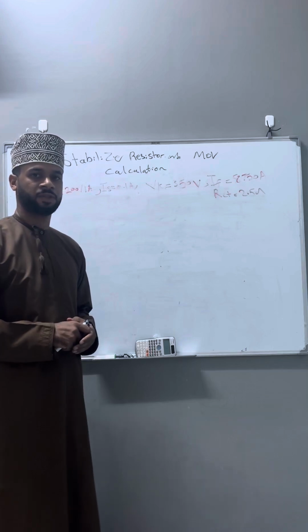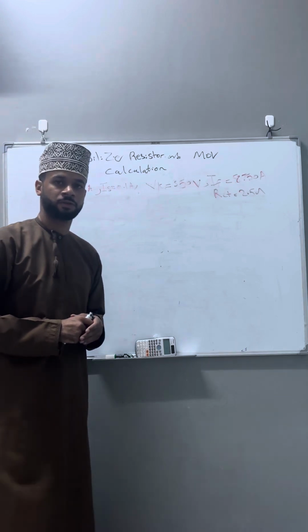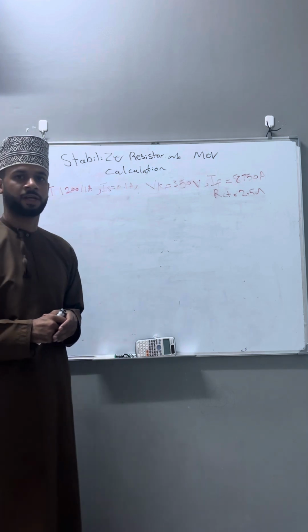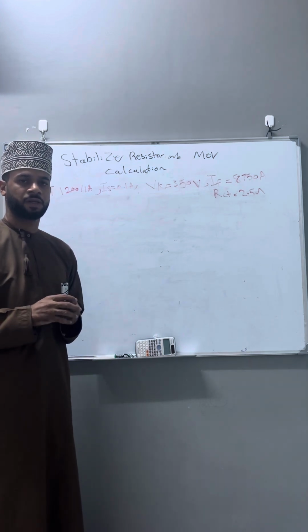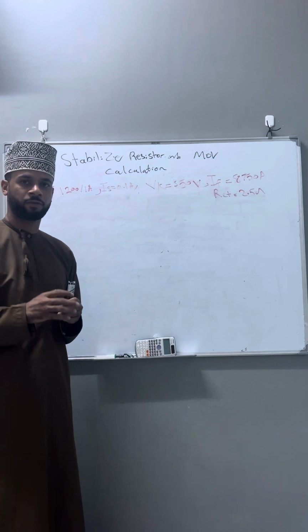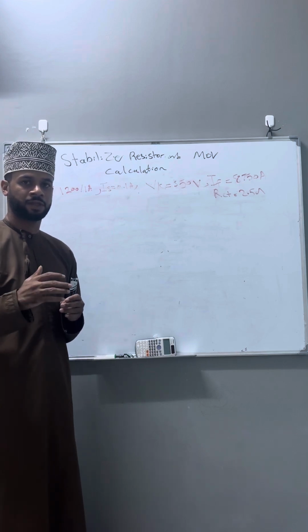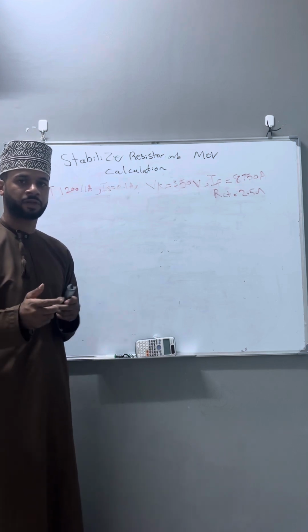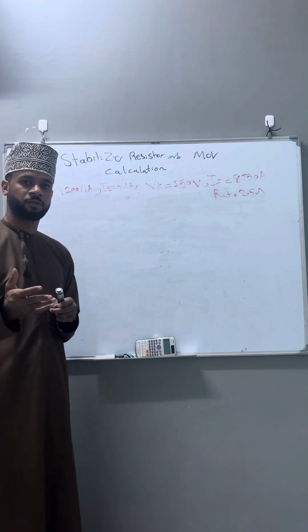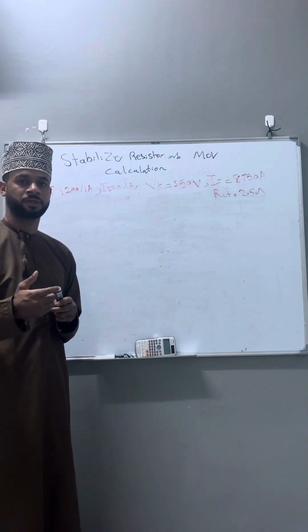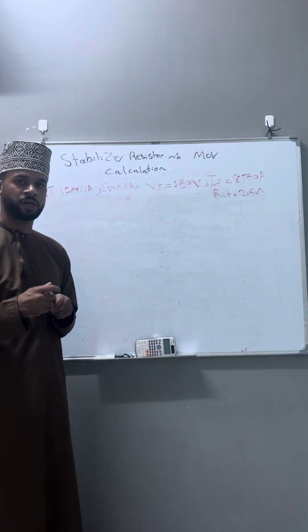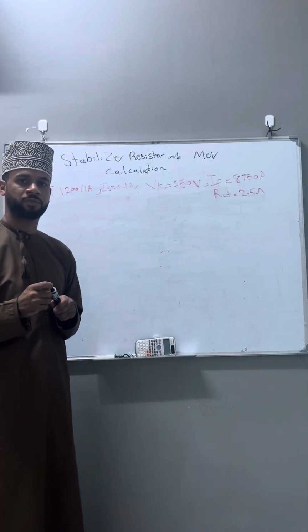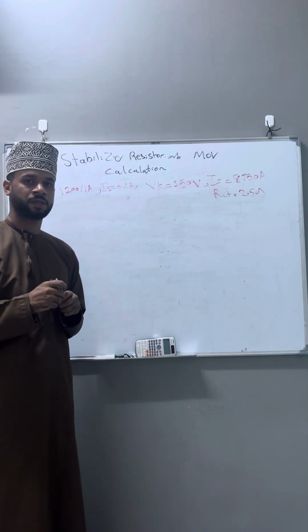Bismillah ar-Rahman ar-Rahim. Inshallah, today I'm going to explain how to calculate the stabilizer resistor and metrosil resistor in the REF protection relay. In the previous session, I explained how the REF will work, and we gave some study cases during internal and external faults, and we saw the purpose of using the stabilizer resistor and MOV resistor. In this session, I will show you how to calculate the stable value of the stabilizer resistor and metrosil resistor.